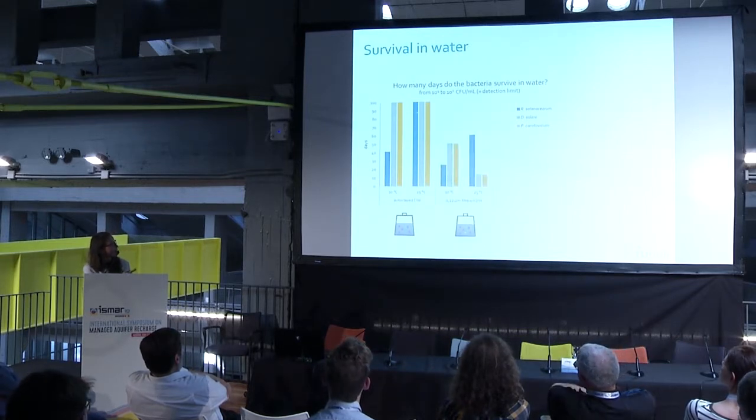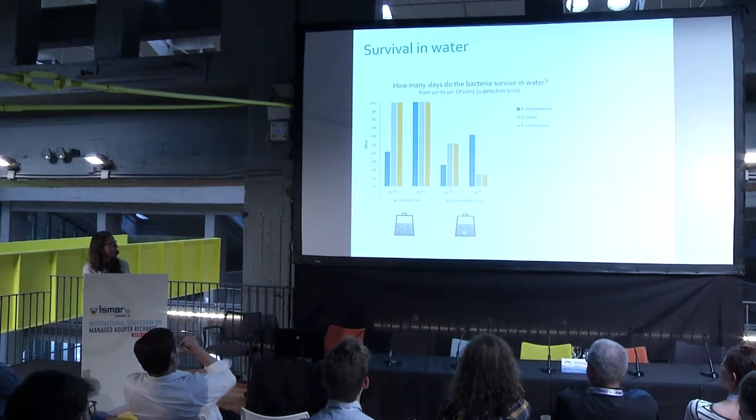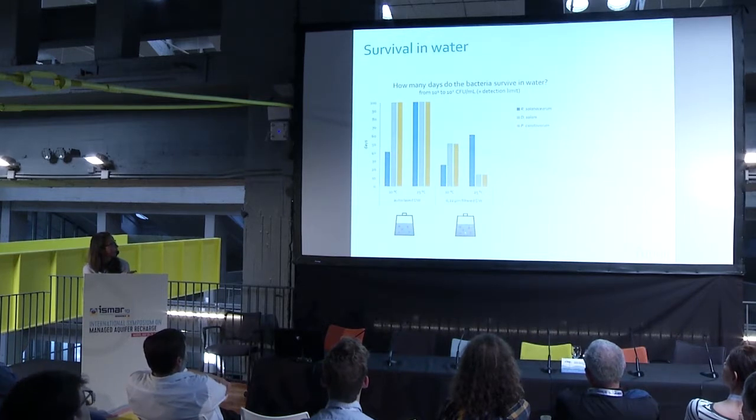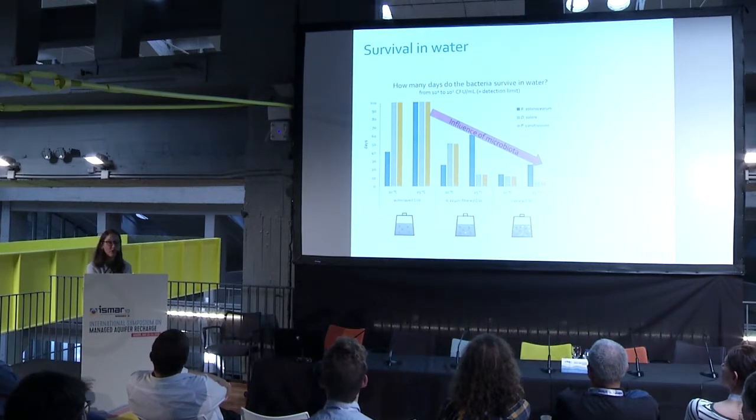And then you can clearly see a trend when there is only the filtration. There are still some microorganisms present, and also the nutrients are not so abundant as here, because here I autoclaved it. And here the bacteria only survive for circa 50 days. And then the influence of the microbiota is clearly visible in the natural system, which would be like the aquifer. So if the bacteria would enter the drain water, they may only survive for up to 21 days.